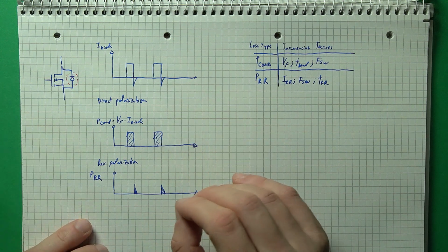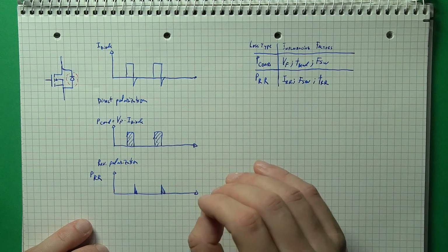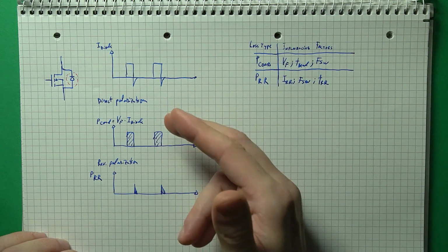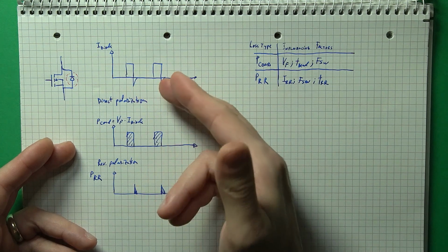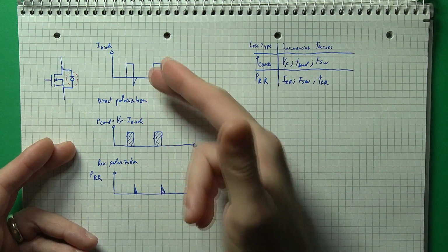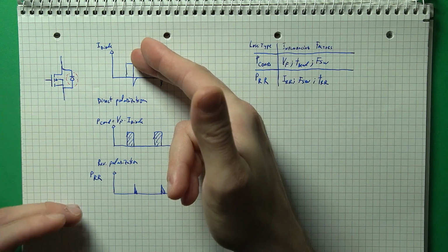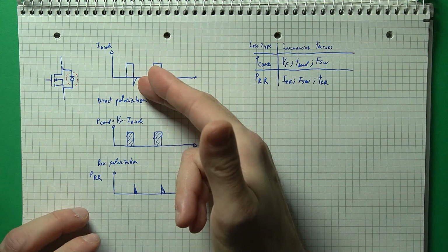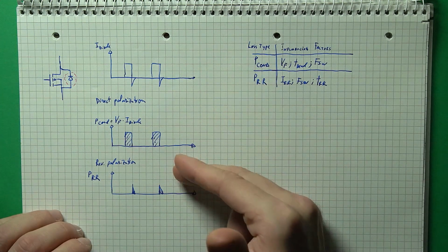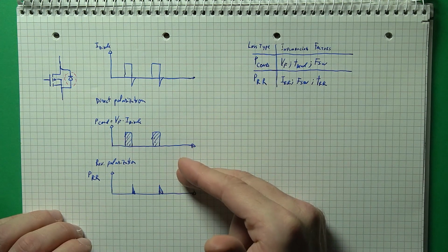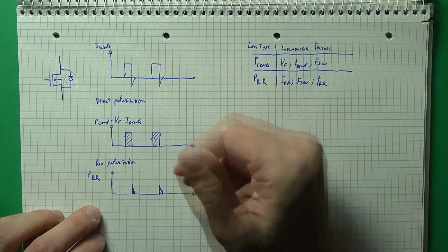And the second mechanism is reverse recovery loss. So this is occurring because the diode ends up conducting the other way for a short amount of time when polarization is reversed. So the current from a direct value will go negative for a while and then go to zero when the diode is blocking. So this reverse recovery loss is occurring because of this reverse current.